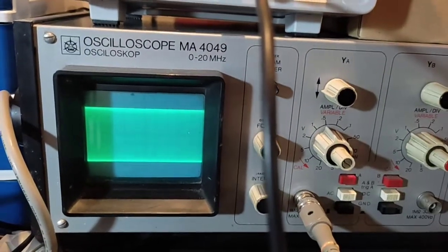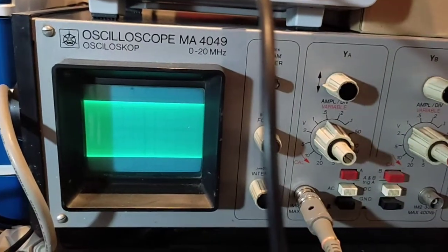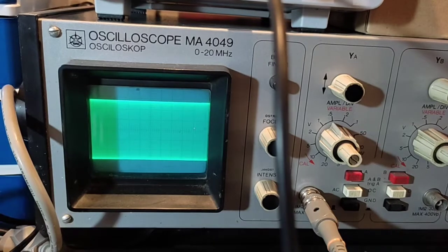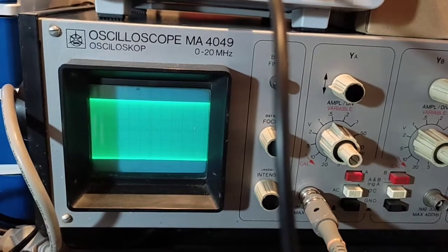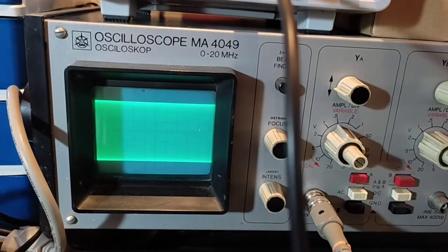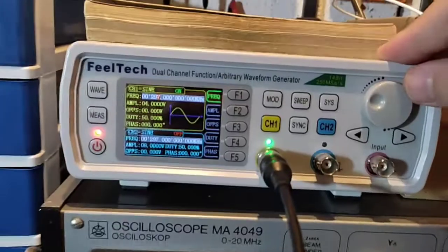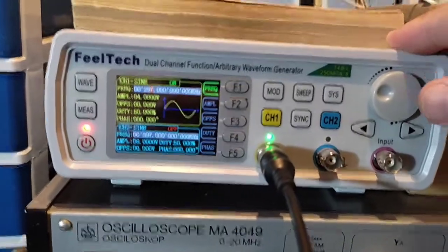That should be it. Now you just watch for the amplitude. It goes up, down, and there's the maximum. So yeah, it's somewhere about 296 to 297 kilohertz.